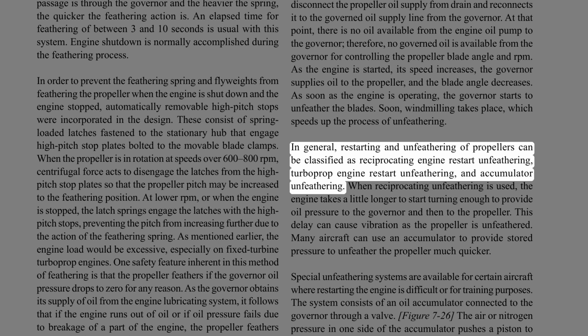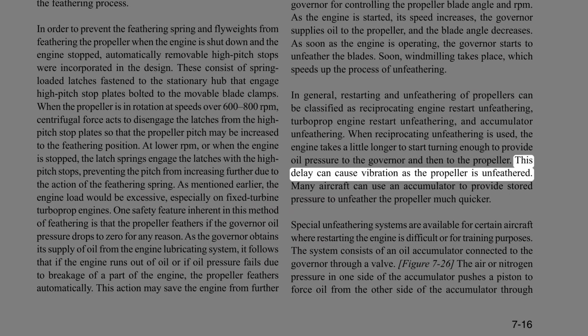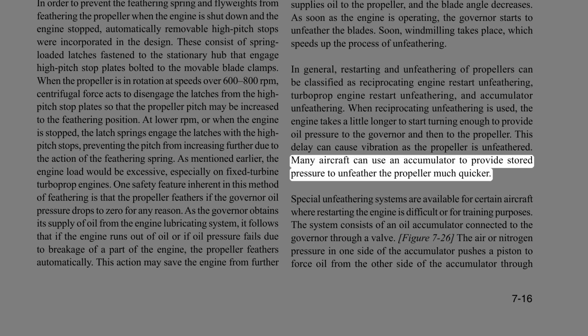accumulator unfeathering. When reciprocating unfeathering is used, the engine takes a little longer to start turning enough to provide oil pressure to the governor and then to the propeller. This delay can cause vibration as the propeller is unfeathered. Many aircraft can use an accumulator to provide stored pressure to unfeather the propeller much quicker.